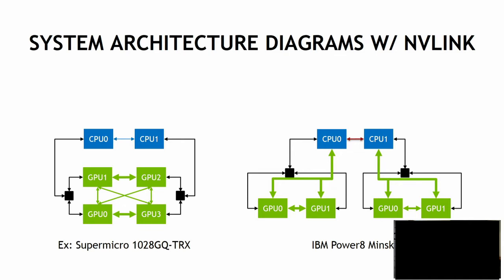So you have 2 GPUs on one side connected to one CPU across PCI Express. You've got 2 GPUs to the other one. The wider lines between them represent multiple NVLinks. And so transparently, the links will be used together for you based on the peer-to-peer protocol. So if you're transferring, for example, from GPU 1 to GPU 2, you would realize 80 gigabytes per second, in theory. With protocol overheads and efficiencies, that'll probably come down to about 72, but that's what you should see.